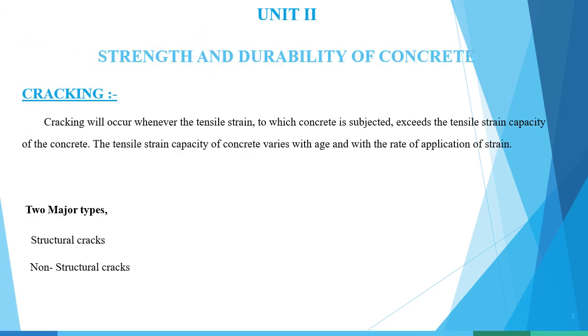Good morning to all. This is Unit 2, Strength and Durability of Concrete. Let me discuss cracking of concrete. Cracking will occur whenever the tensile strain to which concrete is subjected exceeds the tensile strain capacity of the concrete. The tensile strain capacity of concrete varies with age and with the rate of application of strain.